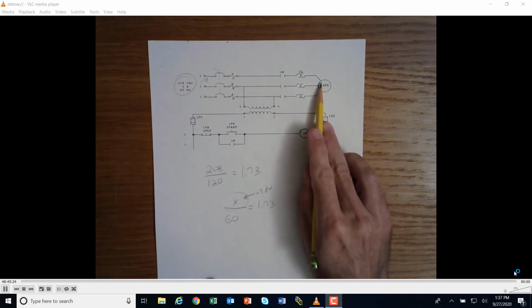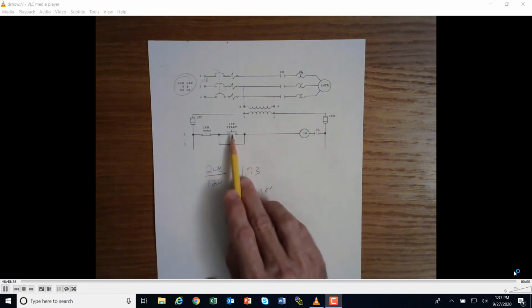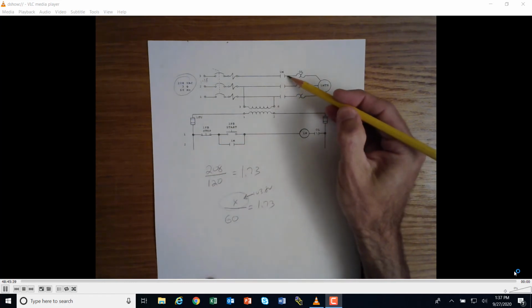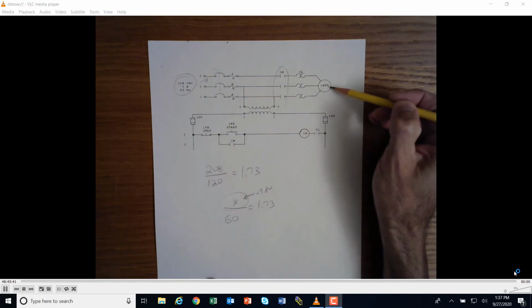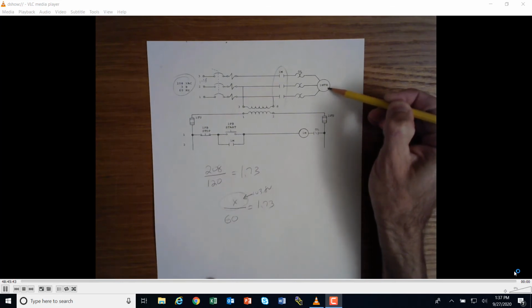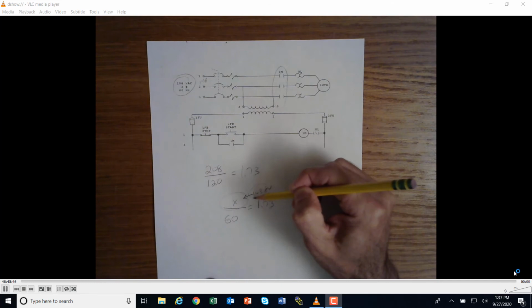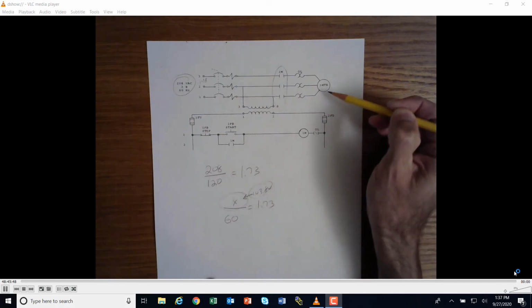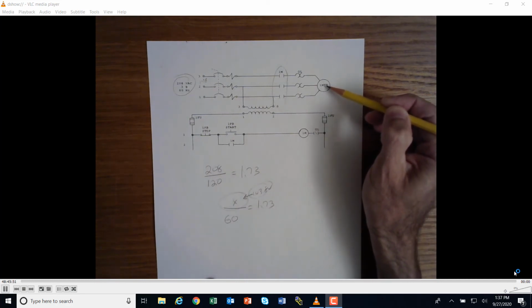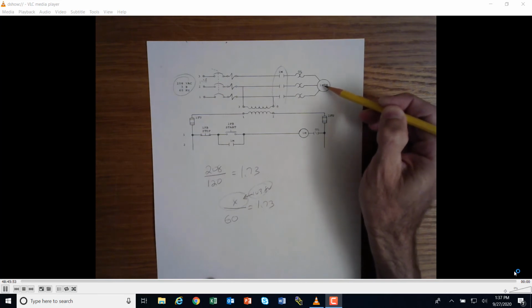It will also maybe start making noise, and it might not have enough voltage to actually run the device that it's hooked up to. So that means it might stall, okay? And at that point, this might not have dropped out yet, opening these contacts here. So this motor might be running at some really low voltage, 103.8, even if it's 110 or 115, 120, that's possibly going to damage this motor right here, and it would cause it to either burn up or run really hot.